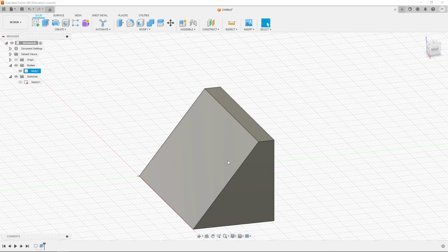So we had vertices, or single points in 3D space, a vertex. Edges are connections or lines between two vertices. Faces are actually closed shapes on a body. A profile is also a closed shape, but still potentially 2D. And then a body is a 3D object that may be composed of many faces. Right? So there's our 3D object.